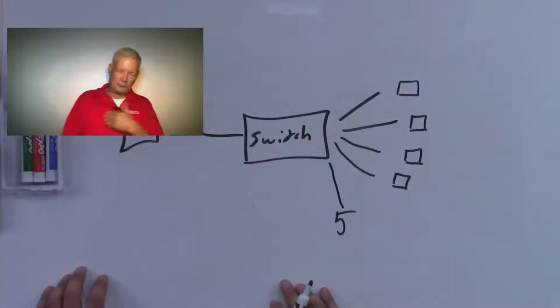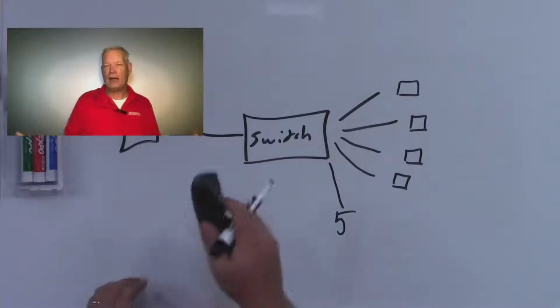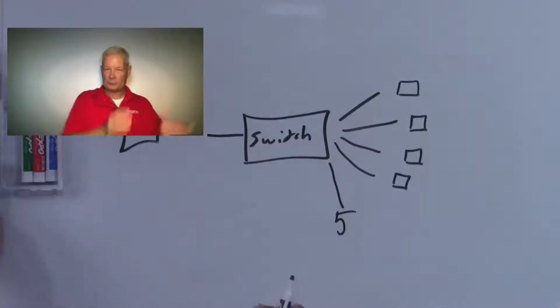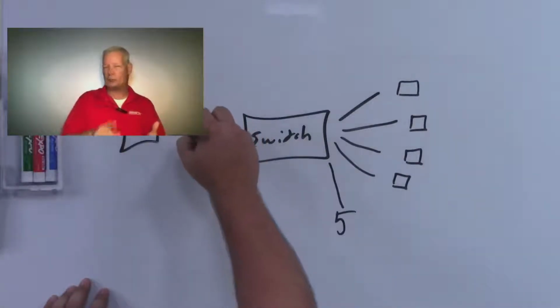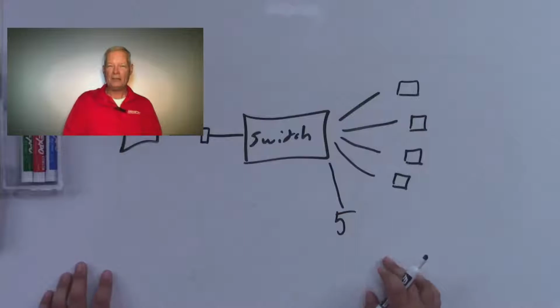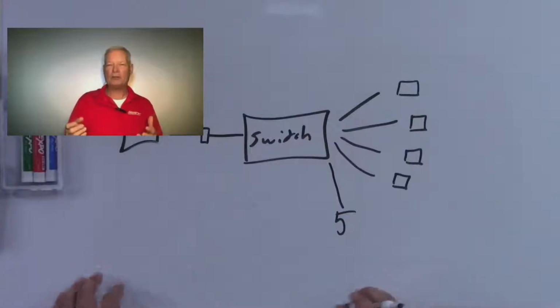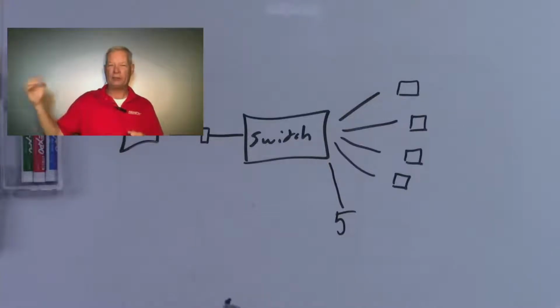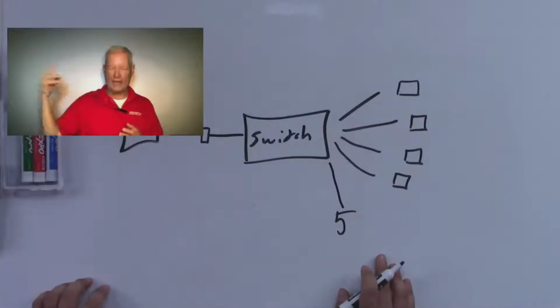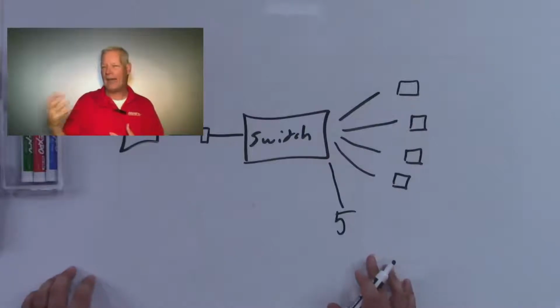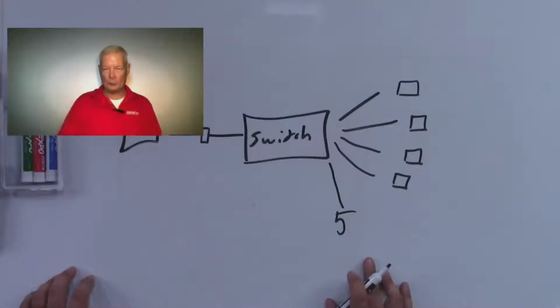So as he was back there, it's like, tell me what all you've got. We want to know the entire system, start to finish. Are there jacks? Are there wall plates? Are there couplers? He had an inexpensive Amazon-type HDMI coupler behind the television to extend the length of the cable. So that was the culprit. When he pulled that out, everything worked.